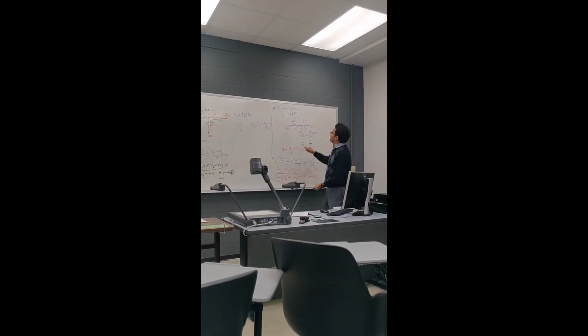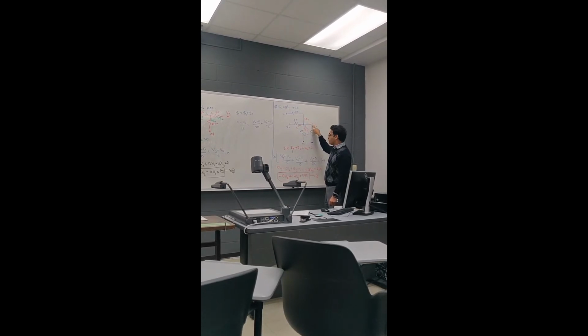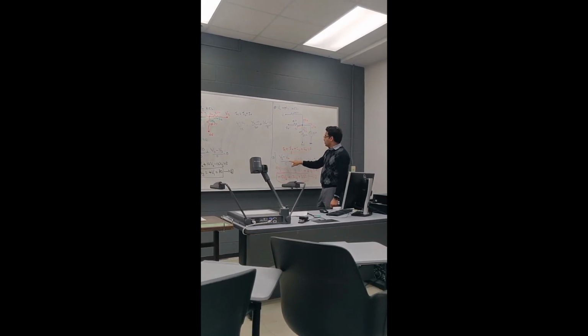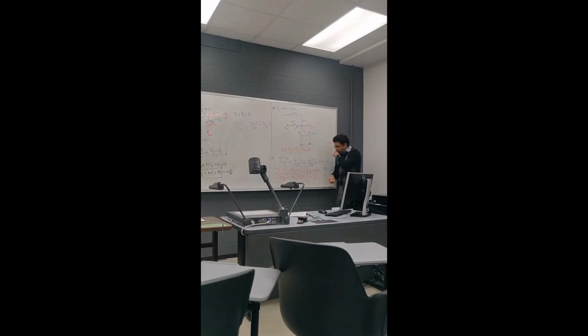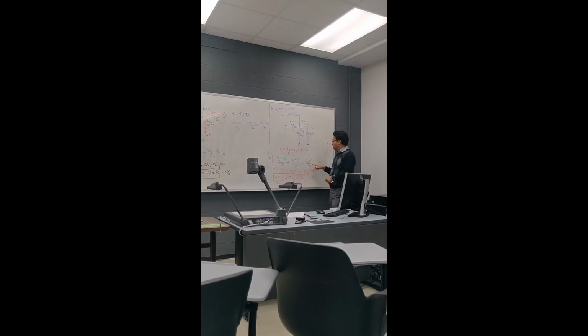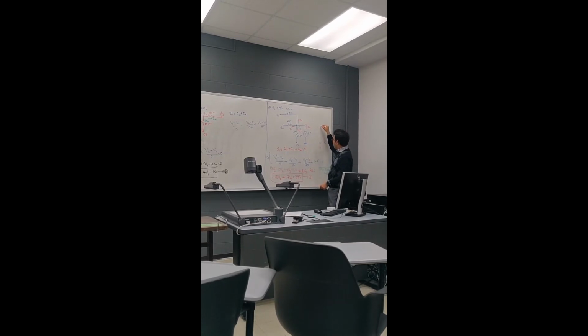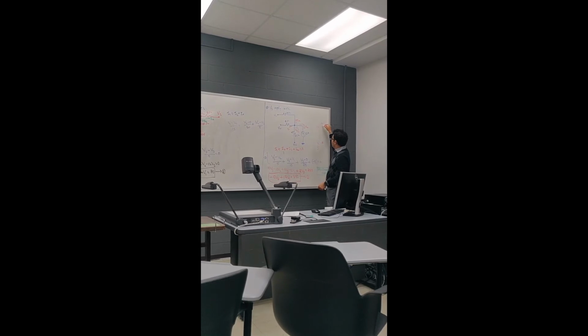In the same way, at V3, apply KCL. At V3, I have 4 elements connected. So I1 plus I2 plus I3 plus I4 equals 0. I1 equals V3 minus V2 over 5. I2 equals V3 minus V1 over 10. I3 equals V3 minus 0 over 25. I4 equals negative 5.